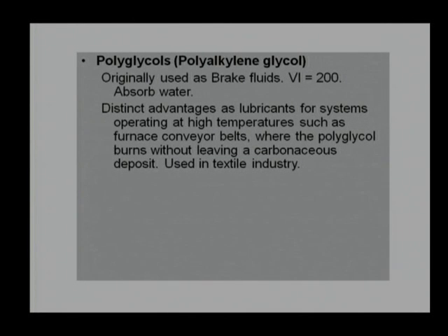VI is almost 200, and they have been utilized as brake fluids. We tried to utilize this kind of polyglycol in our magnetic bearing setup, where the desire was low lubrication requirement and film thickness was maintained by the magnetic repulsion. If we had used a high viscosity oil, there would have been much more shearing of that oil, much more heat generation, but we used a brake fluid which has low viscosity, a viscosity equal to 2 centistokes at 100 degree centigrade.